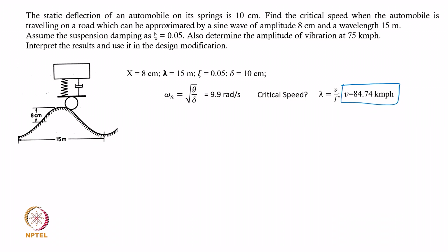And are you clear now what omega is in this case? That omega is going to come from your lambda and, of course, the cruising speed v. If you have a very low cruising speed, this motion is going to be followed at a very low frequency, and if you traverse that profile very fast, then the wheel is going to move back and forth very fast. That is how omega is indirectly linked to the wavelength and the cruising speed v.